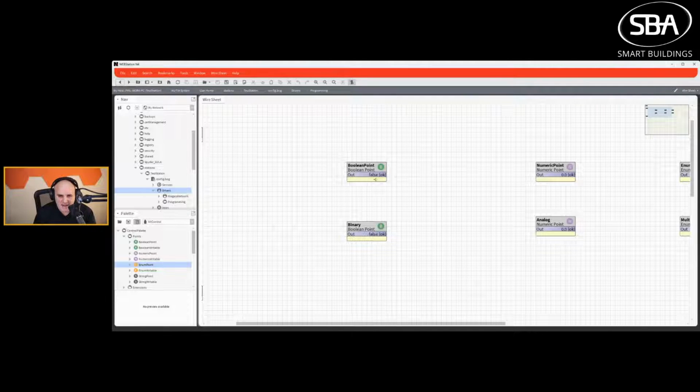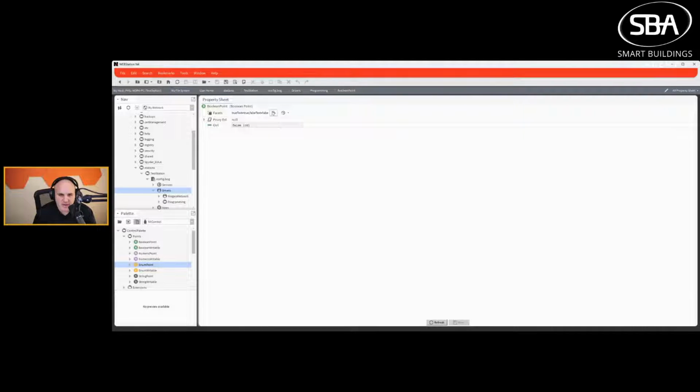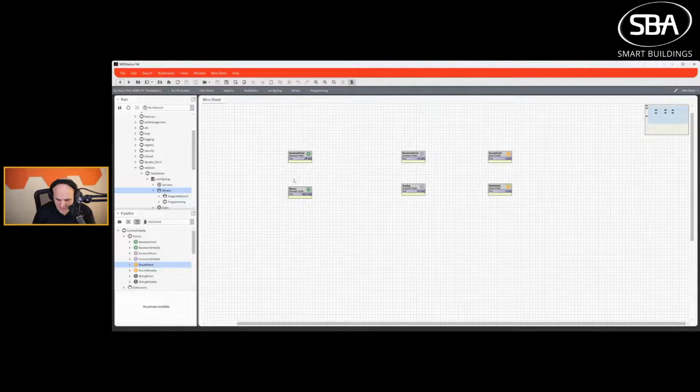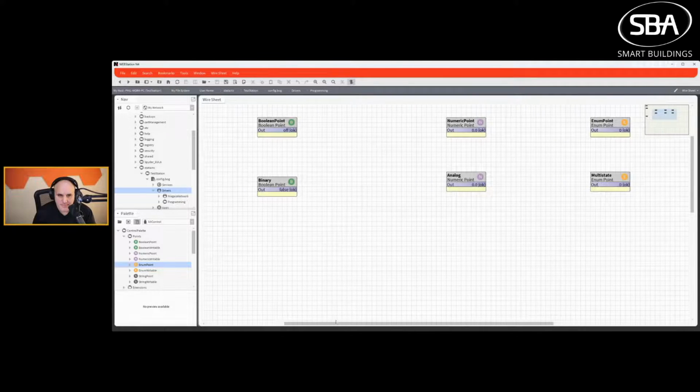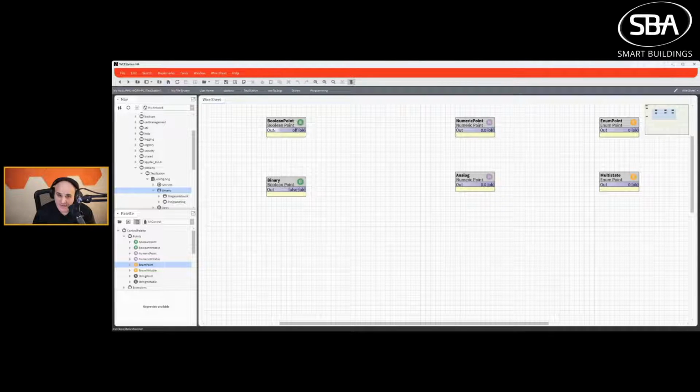They may not attach, like, oh, fan command or fan status false. What does that mean? Does it mean the point failed? But if I go in here and say on, off, and I go back, what we're going to notice now is that this is going to be on, off. So it makes a little bit more sense.